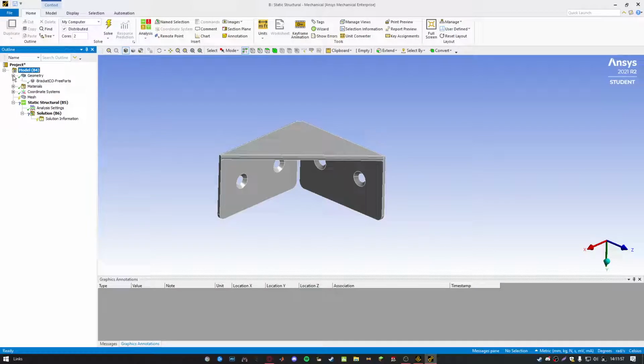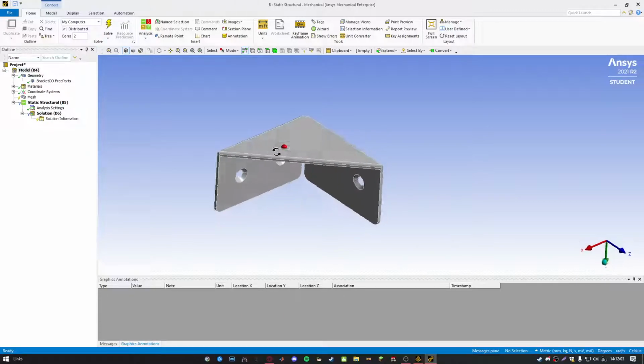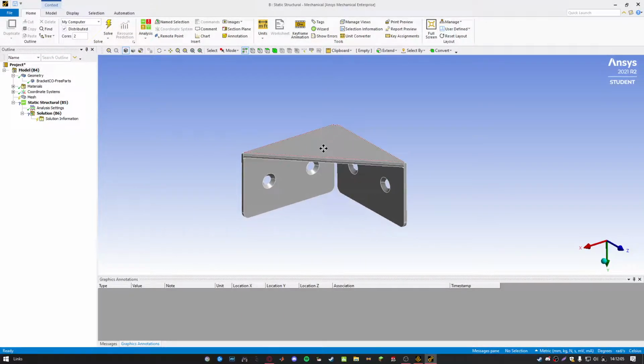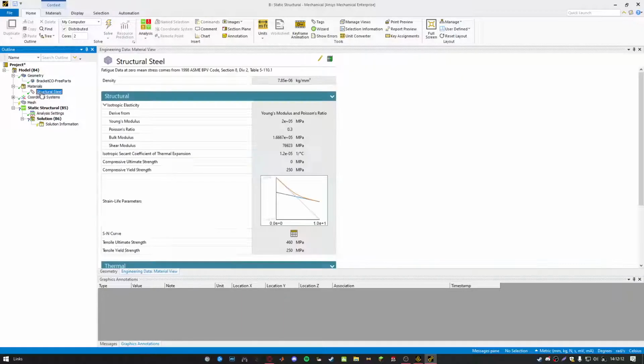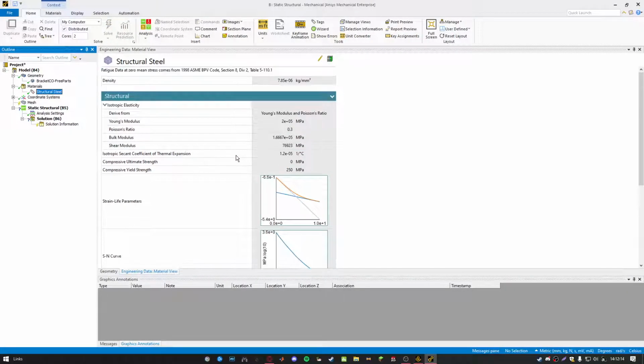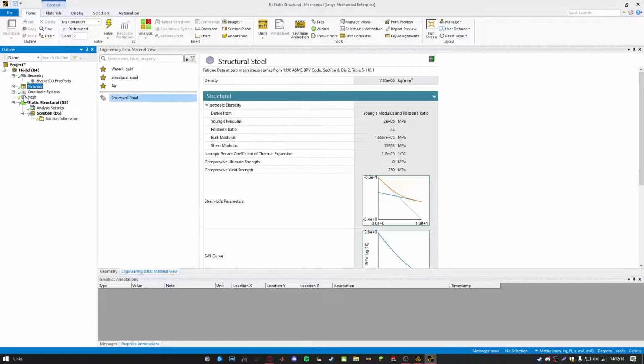First thing you'll do is check the geometry. You want to make sure that little cube is there with the check mark. That means your geometry is solid and it's not hollow. I had that problem. You click on it, it'll highlight it all green. Go here, make sure the materials is right, and it looks like it is, so we'll uncheck that.